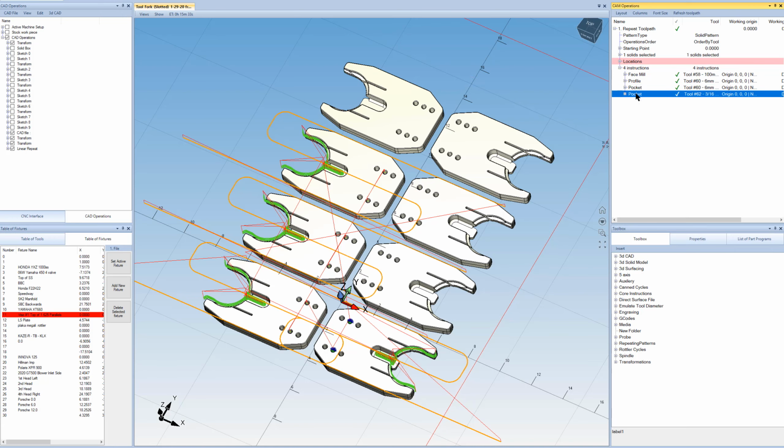And then the pocket over here, since there's only one toolpath in one tool, it's just going to go through and cut all the parts one at a time. So it might take a little bit of experimenting to really have a good feel for what this option does here, but order by tool is probably the most useful. Okay, so I hope that helps. Thanks.